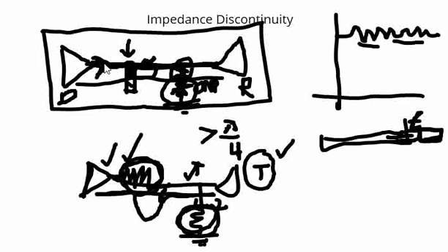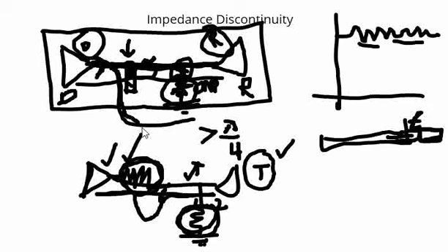Also ensure that when you are connecting, you connect starting from the driver to the receiver, and you eliminate any unnecessary deviations from the signal, like having another trace, which is like a star kind of routing, or basically multi branches. These kinds of scenarios, try to avoid. This is one more thing which needs to be avoided to eliminate unnecessary reflections on the board. These are some of the things which cause impedance discontinuity, and some of the care that needs to be taken to eliminate impedance discontinuity.